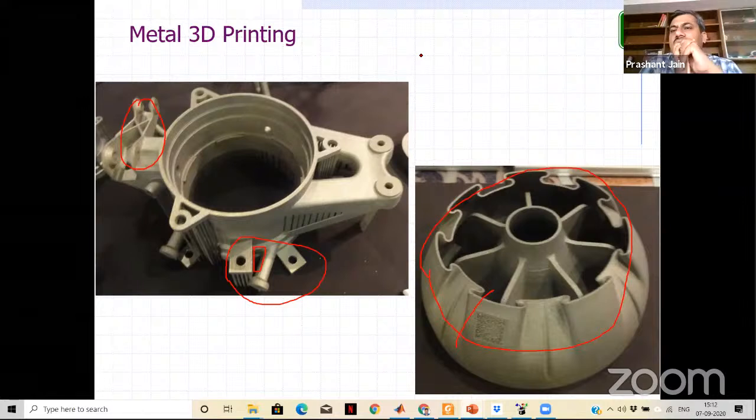The neck formation characteristics have been lost after one heating cycle, so that powder of the steel material cannot be reused. And further, these kinds of components join with the build platform, so you need to cut them with the wire cut EDM machine, right? So a lot of other accessories are required.